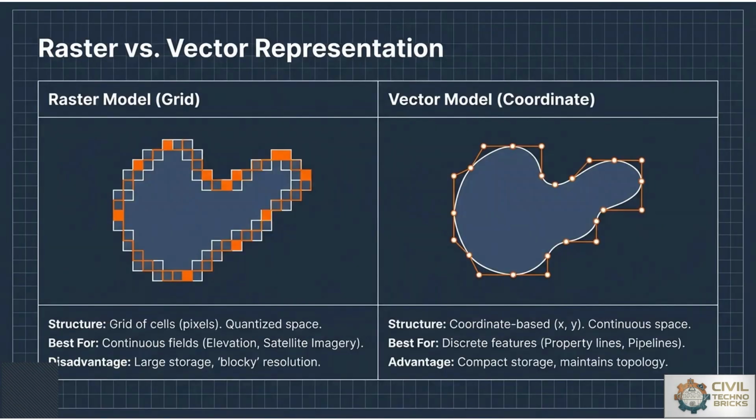The concept of GIS data representation is based on two types, raster and vector. Data representation is the method by which we simplify the complexity of the earth, with its geodetic curvature and the features inbuilt or associated on its surface, into a computer-readable format. In GIS, we represent geography as a series of layers, each layer focusing on a specific theme like road layer, topographical layer, utility layers, etc.